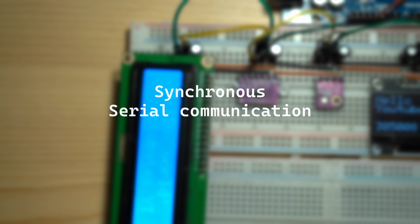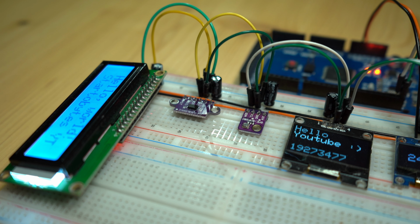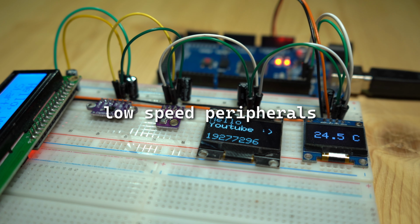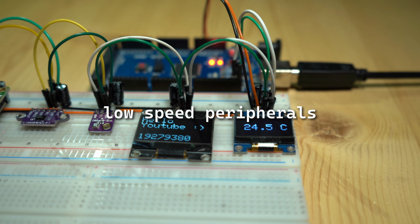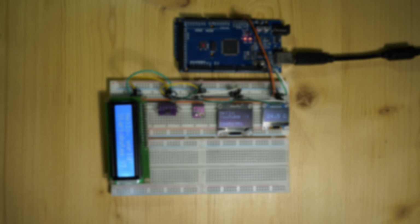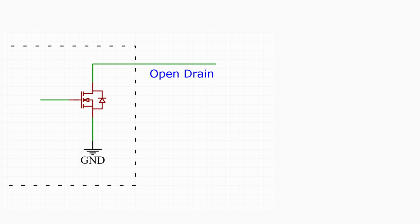I2C is a synchronous serial data communication protocol that is widely used for attaching low-speed peripheral devices to microcontrollers and processors in short-distance communications. As both wires are open drain outputs, pull-up resistors are required.